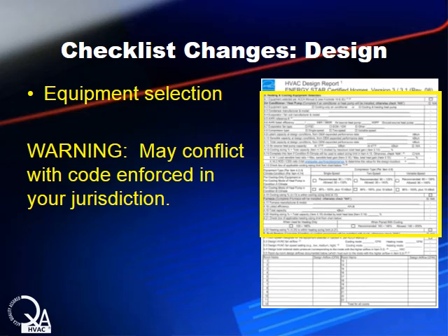and that may conflict with what your local jurisdiction enforces if they're enforcing Manual S, or what the rater can allow, because the HERS rating requires compliance to Manual S. So as a designer, just want to offer a word of advice to check with the rater, check with your local code official, and ensure that you're not going to get yourself in a bind by following this Energy Star expanded tolerances if the other entity is going to be enforcing the stricter tolerances.